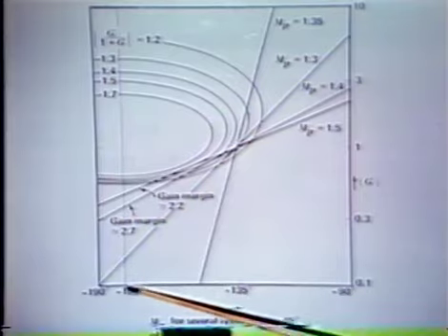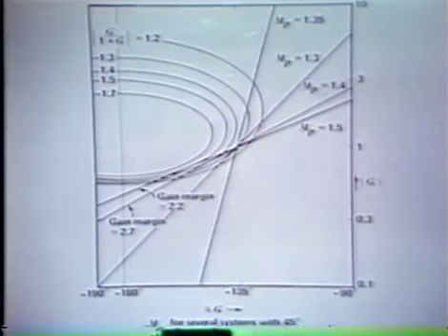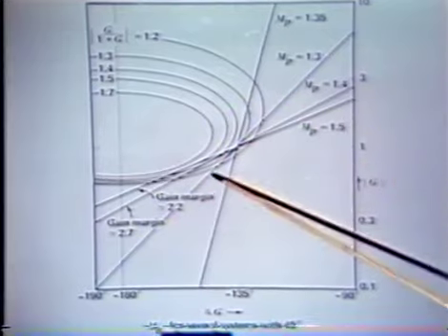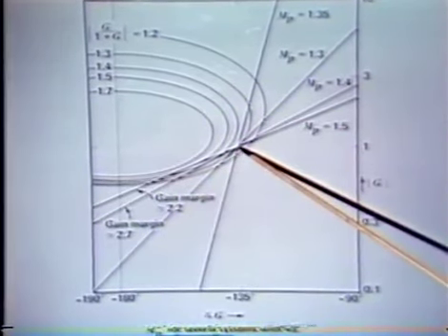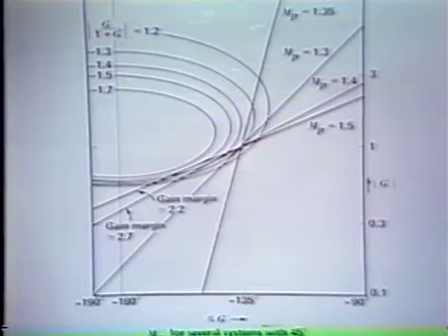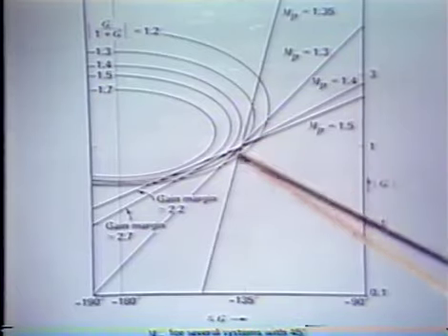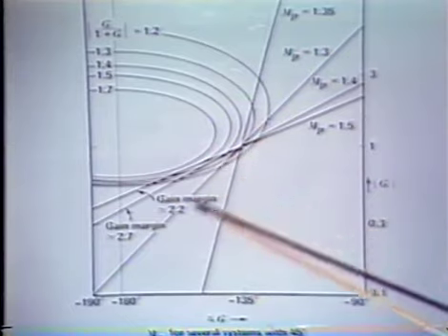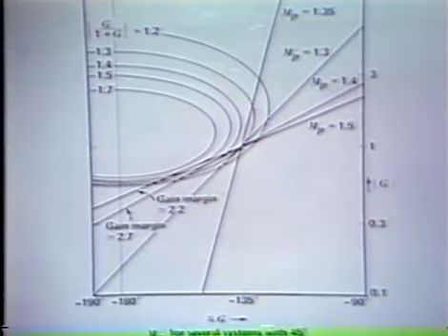We have a phase margin correspondingly of 45 degrees. So all of the curves are constructed to go through this point. Magnitude equals 1, angle equals minus 135 degrees. And we simply have different slopes, approximating different kinds of AF products, all with the same phase margin. And we can now begin to look at the MP, the maximum value of the closed loop response that we get for those various curves.